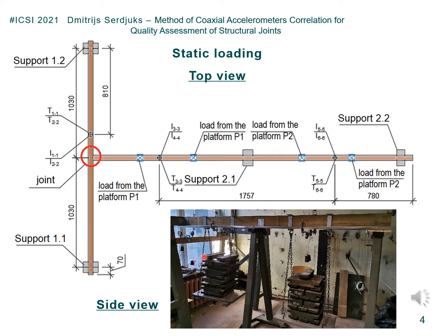to specify the statical scheme of the beam stand and the type of the beam joint. The statical scheme of the beam stand depends on the stiffness of the beam joint, which was varied during the experiment by adding or removing the screws used as fasteners. Six deflectometers and 6 strain measuring devices were used in the course of the statical test to verify the statical scheme of the beam stand. The beam stand also was modeled and analyzed by the finite element method.